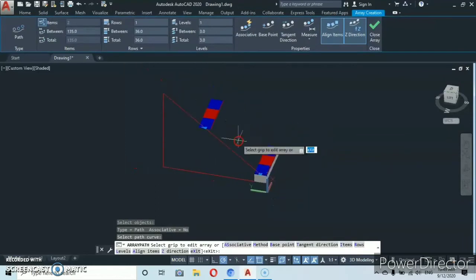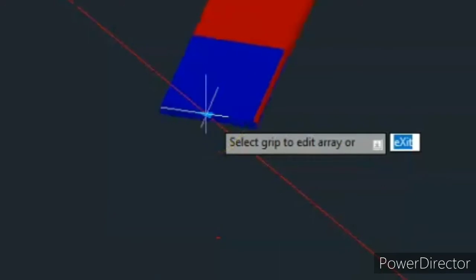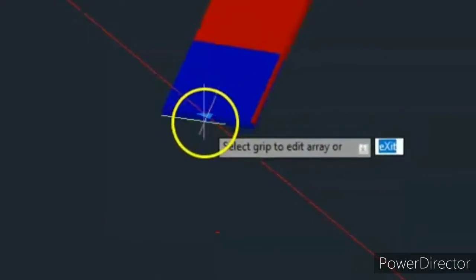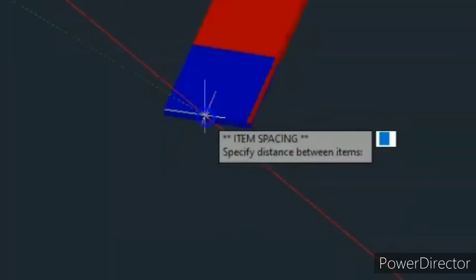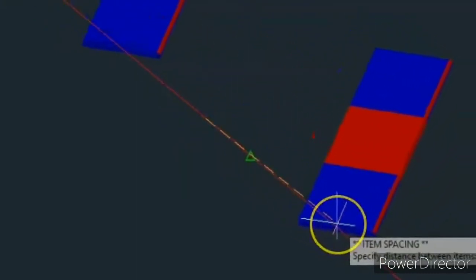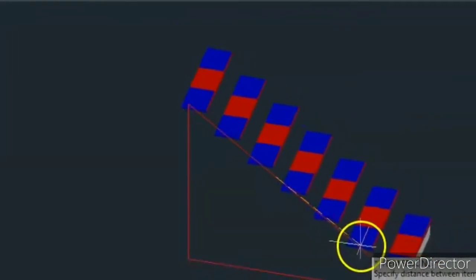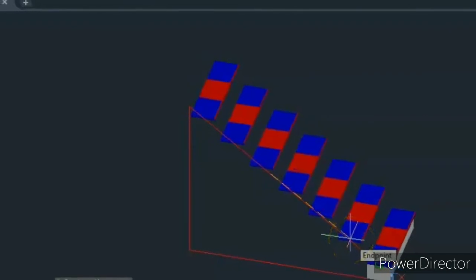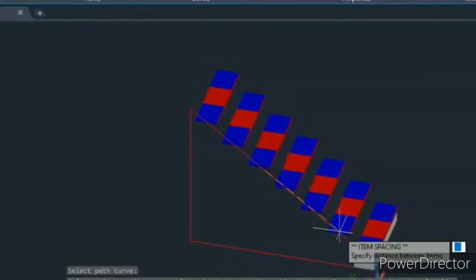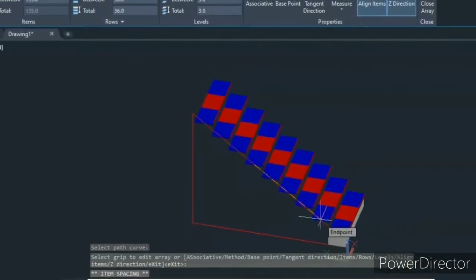Then from here we are going to do our grip array. Okay, so we come up here. Let me zoom so that you really see. You come up here and you grip, left click and let go of your cursor, and you pull. Then you see your steps following down. So you count up to 8: 1 2 3 4 5 6 7 8, plus the initial one.